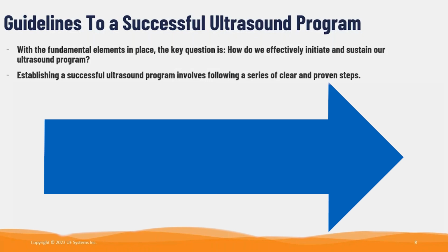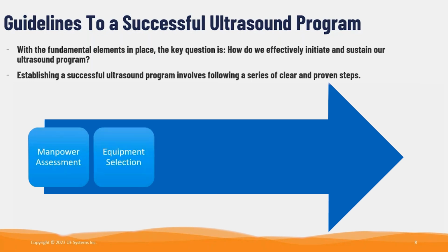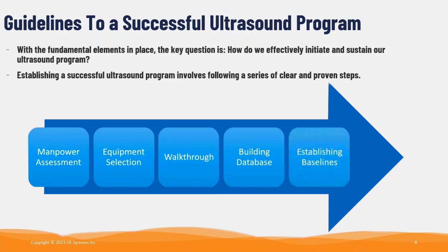Okay, so now if you have all the fundamentals in place, how to initiate the ultrasound program? To start establishing the program, we can follow a series of clear steps. First, manpower assessment, then equipment selection, walkthrough, building database, establishing baseline, and finally trending. We will be discussing these steps in more detail now.